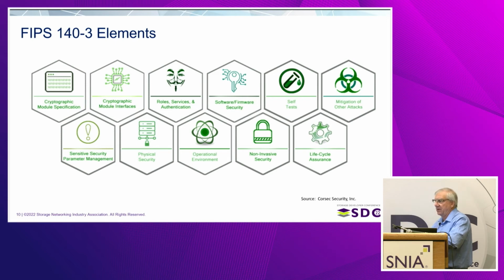There are aspects of physical security in this. I've actually been in a situation where we had a controller board in a product, and we shipped the product for encryption. We eventually got a FIPS certification, and we had to ship a special kit to the customers that wanted FIPS certified product. The kit basically included a piece of tape. Somebody had to slide the drawer out, put the tape across, and slide the drawer back in. It was the tamper-evident seal that was necessary for that particular level.